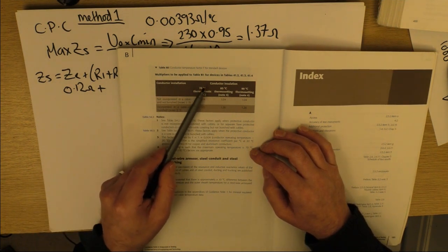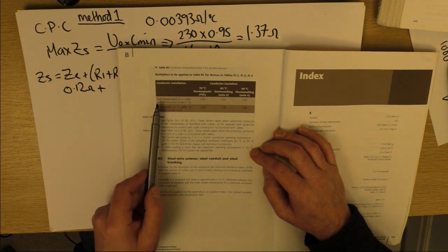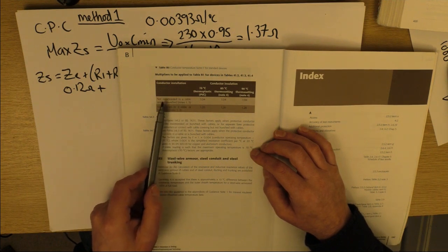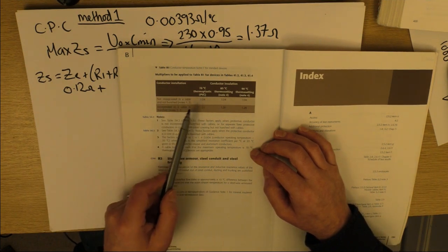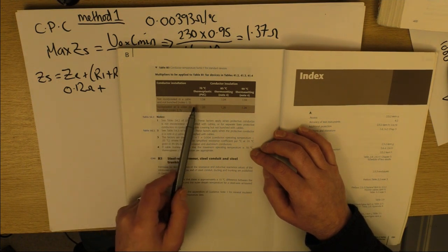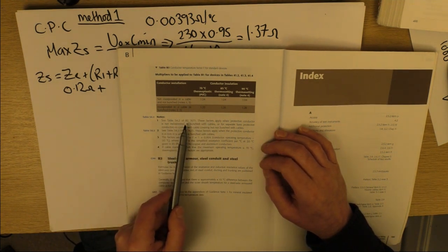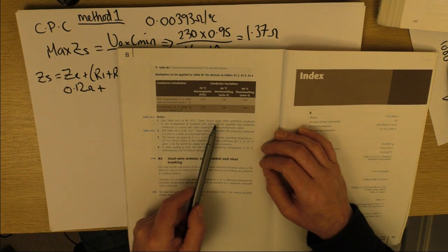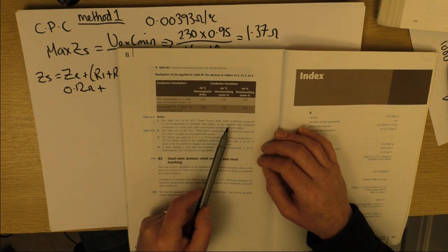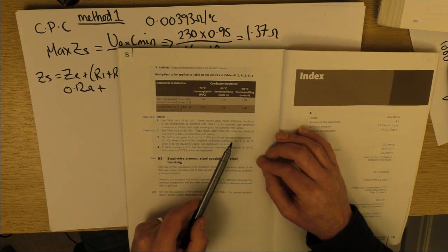So our cable, we went for 70 degrees C, thermoplastic, singles. We've got not incorporated in a cable and not bunched, which sort of leads you to wanting to use that one. And then this one, incorporated in a cable or bunched. Then we've got some notes here, so notes 1 and 3. 1. See table 54.2 of BS 7671. These factors apply when protective conductor is not incorporated or bunched with cables, or for separate pair protective conductors in contact with cable covering but not bunched with cables.